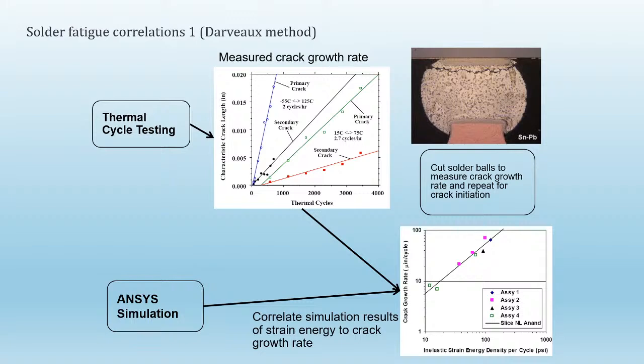Both are totally valid, and this is another key part of what we need to do if we want to capture accurate simulation and accurate fatigue results for solders. Again, as I mentioned before, if we have thermocycling and we have simulation, we can get this type of data of how many cycles it takes to fail, and what the energy release rate is, or the creep strain in the solder in the area of interest.